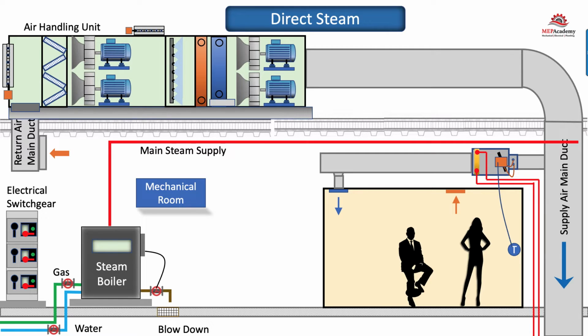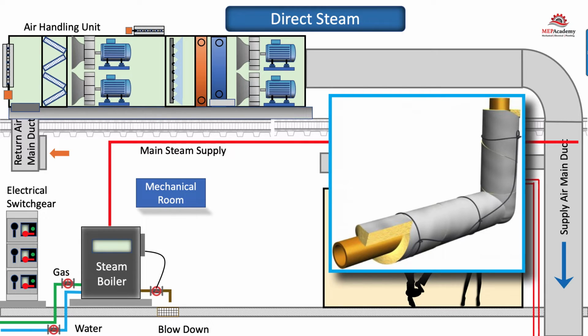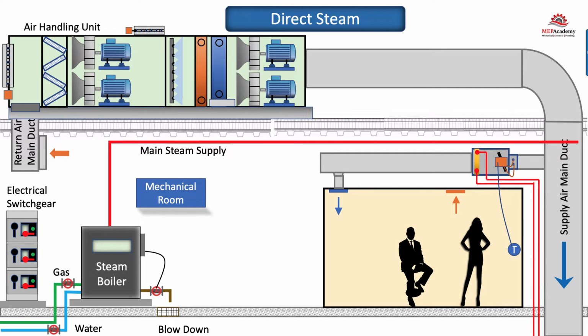These pipes are expensive to install because of the added cost of expensive insulation to prevent anyone from burning themselves if they were to touch the steam pipe and to protect against a loss of steam. Then, most likely, we'll want to use a condensate return boiler feed water system of some type, so as not to waste the condensate which has already been heated.